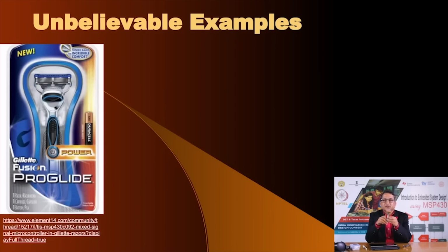The reason why it uses a battery is that when you turn this razor on, the razor head vibrates. Apparently, it gives you a smoother shave. Now, as you keep using it, the battery voltage will reduce as it discharges, and that will reduce the vibration of this razor. To maintain the vibration, they use pulse width modulation, so as to maintain a uniform vibration over the lifetime of the battery. For that, you need this embedded computer.